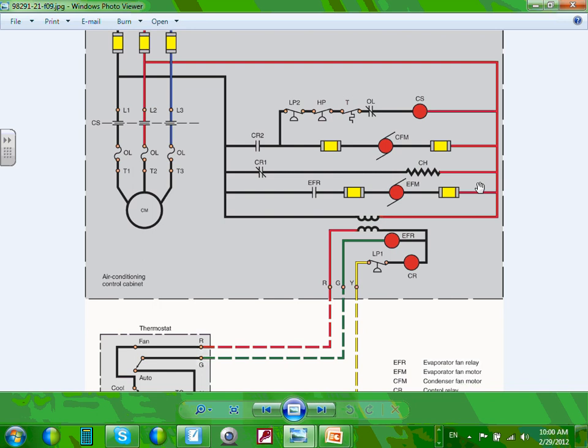So if those blow, the air conditioning guy has to go. If it's not working, you're going to go troubleshoot. If these blow because the compressor or fans are failing, or the overcurrent protection device blows, you have to go change these fuses. There's fuses for these, and there's a fuse for the whole system right here, for the whole package. Absolutely. Any comments, guys?